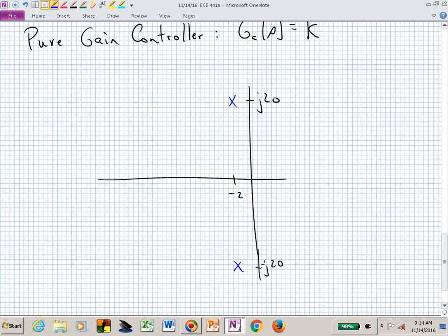If I looked at any point on this root locus, on the real axis, have to wake up, it's Monday. If I looked at this point and I said, what's the phase angle at that point? You would say, well, due to the poles and zeros, I can find the angle to that point from this pole, and it's that angle. It would be negative, I don't know, minus 120. And this angle would be, let's say, plus 120.